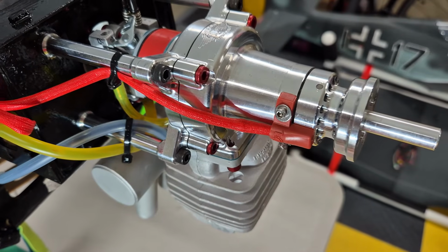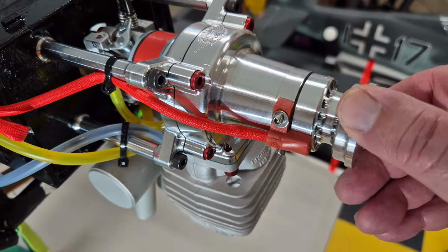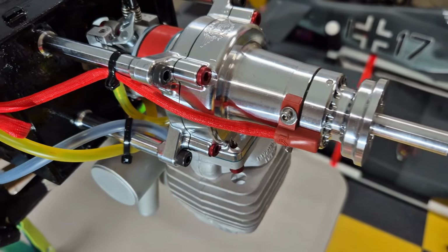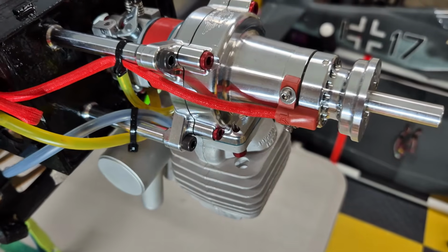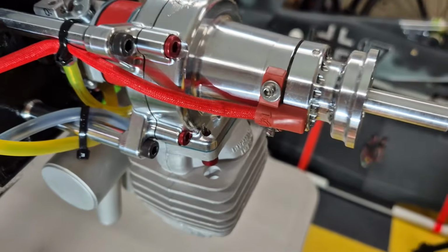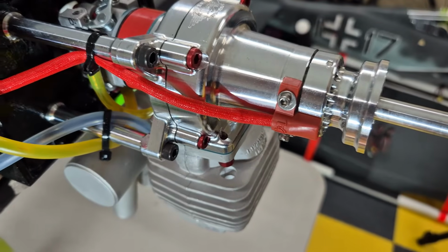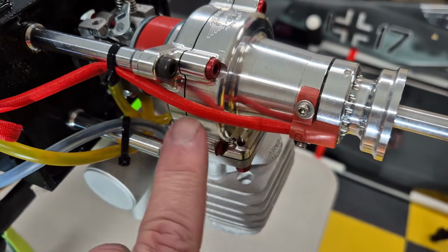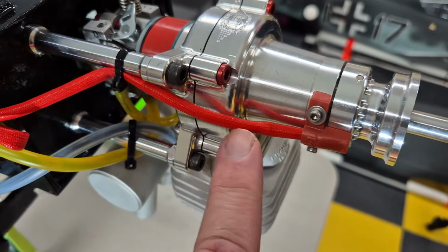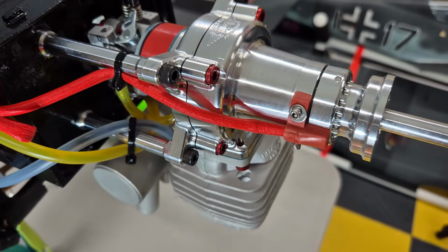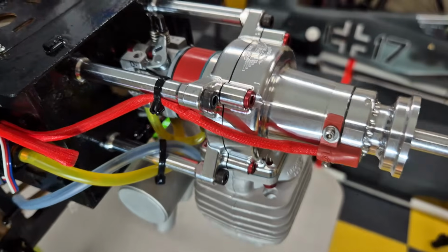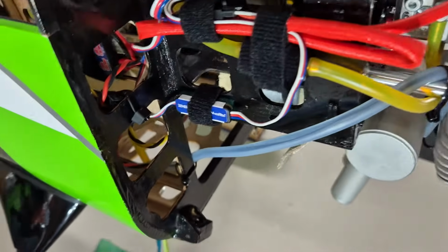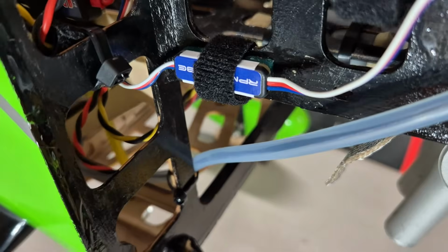So that detects the magnetic field as the magnets go past, and then basically the ignition fires the spark plug when it's at the correct point in time in regards to the crankshaft rotation. So basically there's an RPM output out of here, but how do we get that to my core? To get it to the core, in this particular example, I use a PowerBox RPM probe.